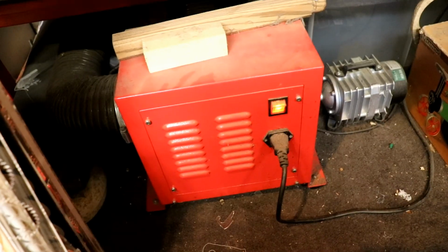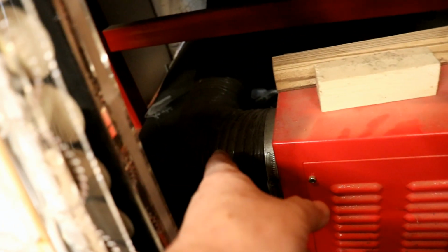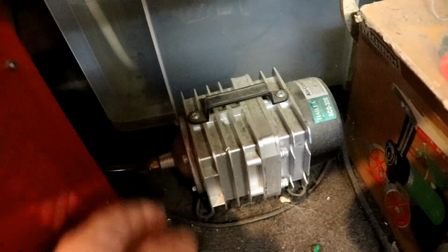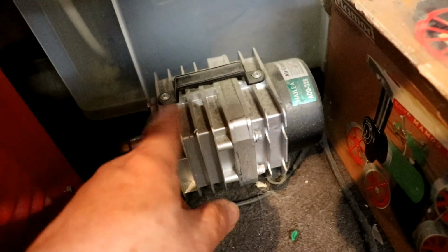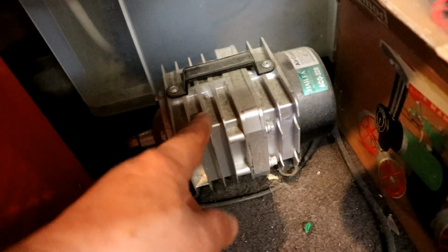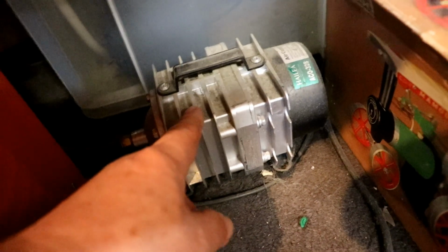By the way, the noises that you can hear that the laser cutter makes are produced by the big blower that sucks the fumes away and blows them outside. A lovely little air compressor, or air pump, blows air through the cutting nozzle to stop smoke getting up and making it dirty. And coincidentally, there's the tank for the cooling water in the back. It's just a storage container with a pond pump in it that circulates water through the laser tube.